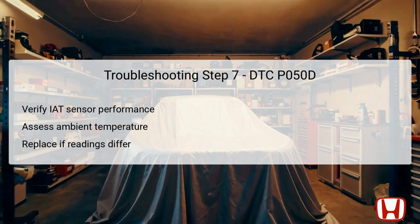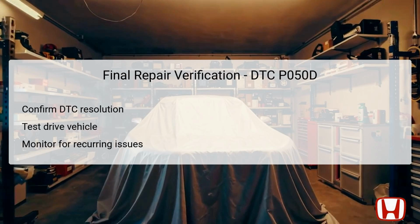However, ensure to check for any dirt, carbon buildup, or damage within the throttle bore, as cleaning or replacing the throttle body may be needed depending on the assessment. After completing the necessary repairs for DTC P050D, a final verification phase must be performed. Use the HDS to confirm that all DTCs have been resolved, ensuring that the P050D and any other associated codes